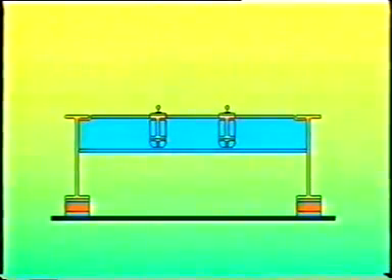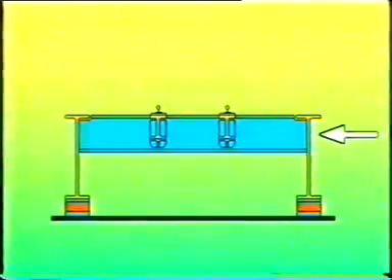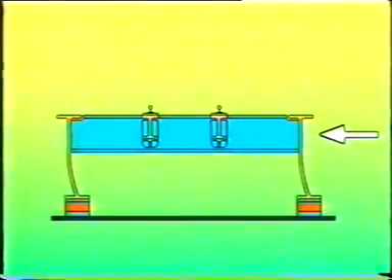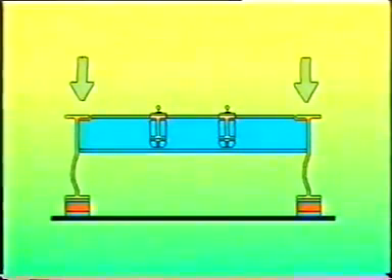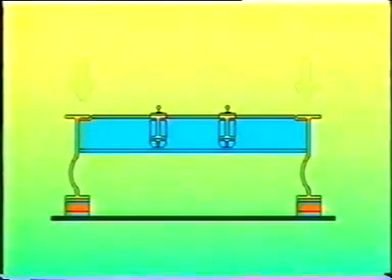An important concept is the U-frame stiffness, in particular at the supports of a deck girder bridge. Due to the horizontal wind loading, the lower part of the web may suffer large deflections. Vertical forces at the support, which cause compression in the web, might lead to instability.